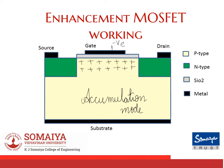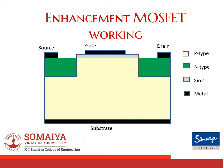When you apply a negative voltage, you will have holes, the majority charge carriers in the p-type substrate, building up at the silicon-silicon dioxide interface. So in this case, you will have accumulation of charge carriers, but there will be no current flow. This is a mode of operation where there is no current flow when you apply a gate voltage that is negative.